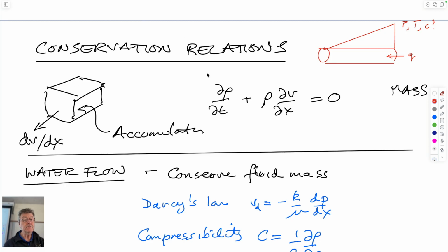And so in all of these, we use conservation equations. To link all these together, a generic conservation equation defines mass transport within the system. A conservation equation takes a differential bucket and looks at the density, the mass of fluid within that bucket. If you put more mass of fluid into that than you take out, then you accumulate mass, and that accumulation is given by this term as a result of the mass rate in versus the mass rate out being balanced with the accumulation.